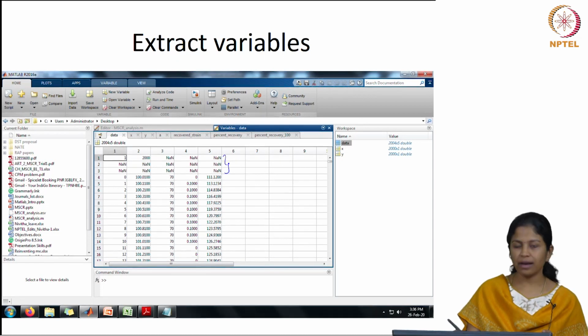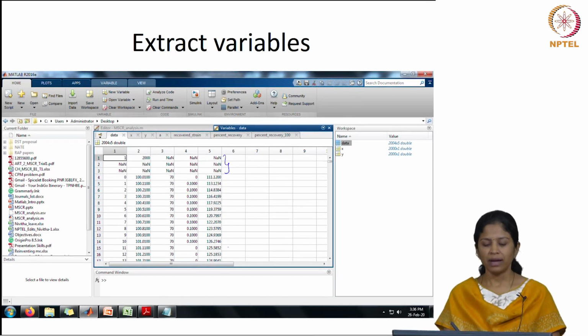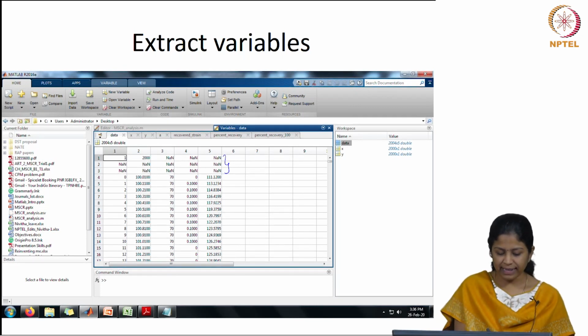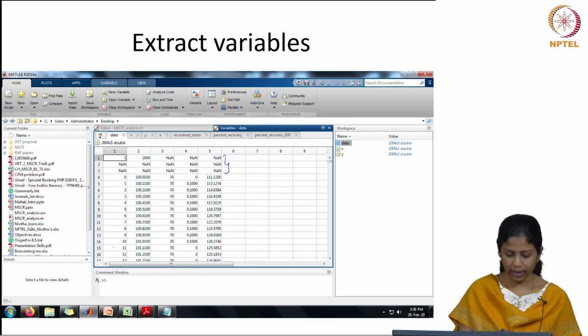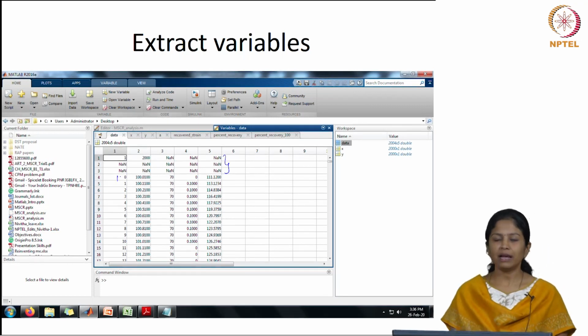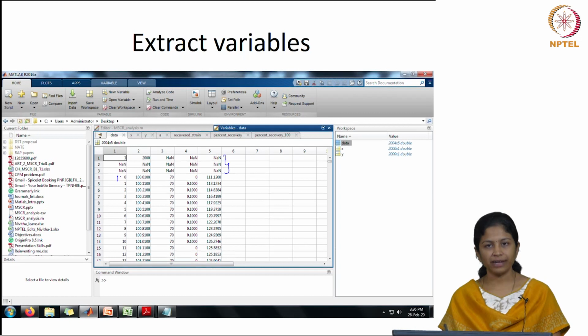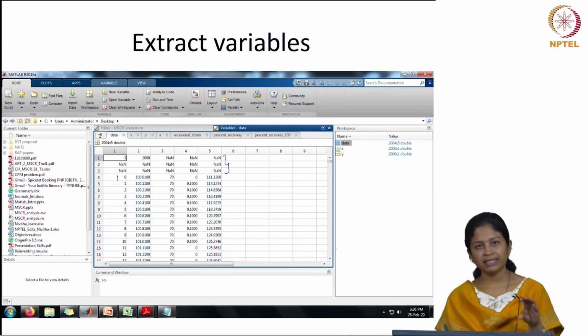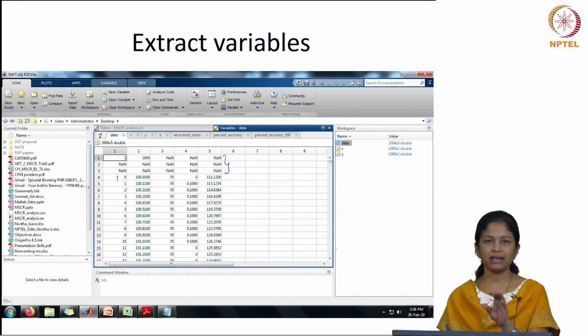The first 3 rows are not numbers; they have some string information about the experiment, and the data starts here, right. I have added one more point. Generally in a multiple stress creep and recovery test, we perform some pre-shearing, like 10 cycles at 0.1 kPa and 10 cycles at 3.2 kPa, as we have said.